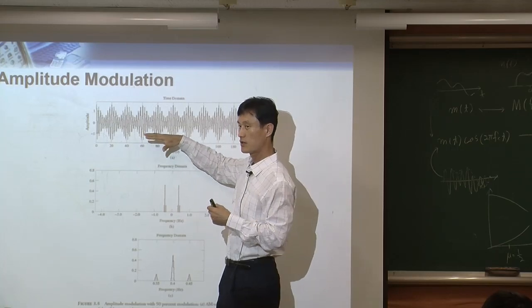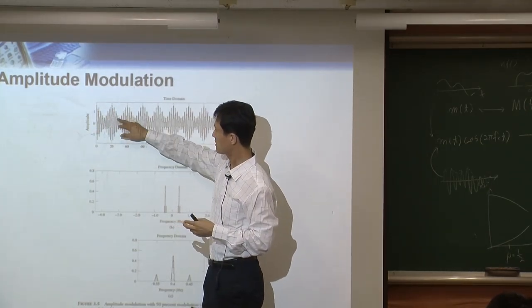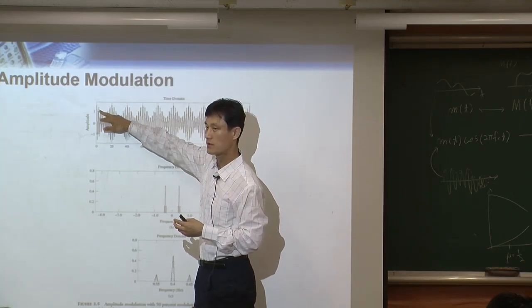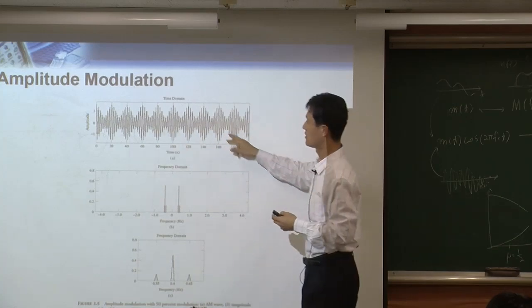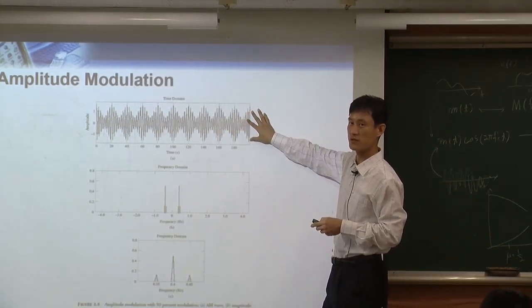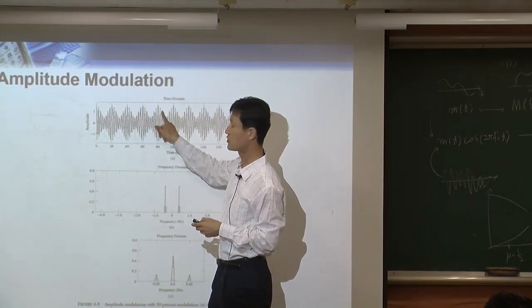Now in time domain, you lift that up, and you see that all the message in time is now well above the 0. It's all time domain. So in this case, it's very easy to use envelope detection because you want to recover this signal. That's your message.